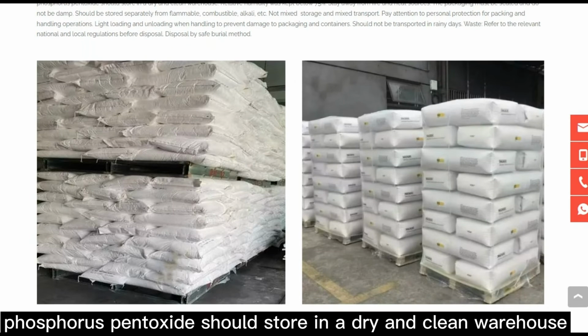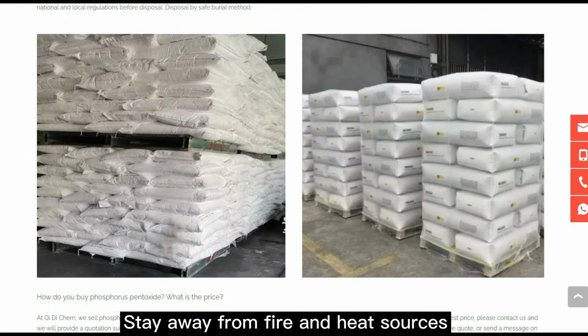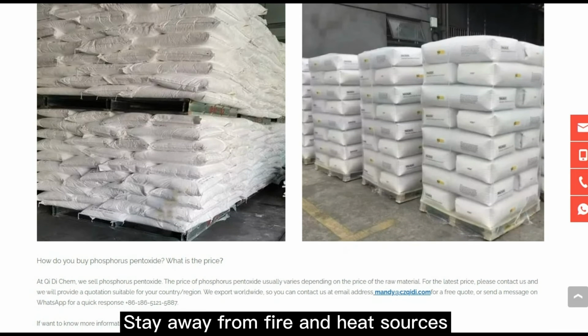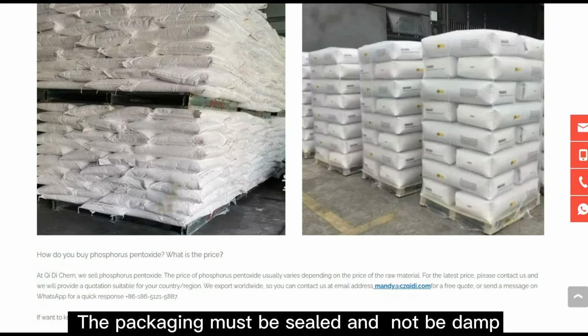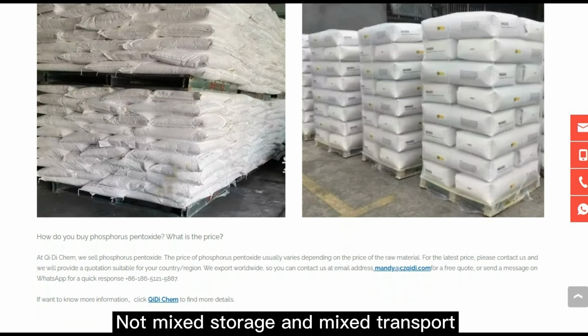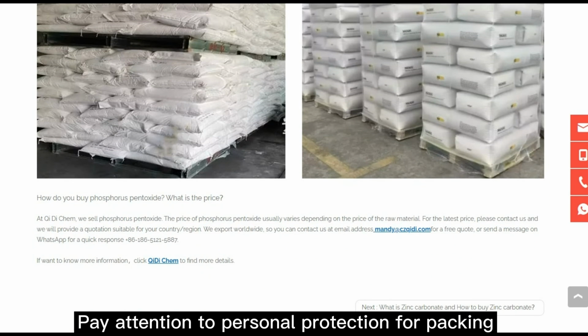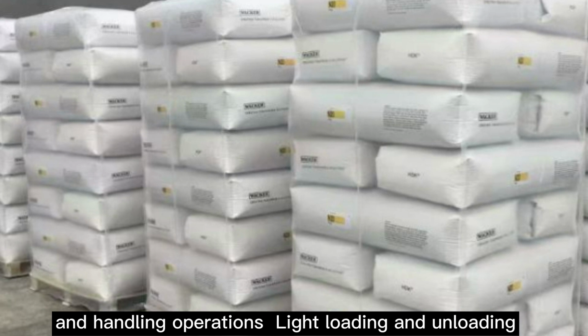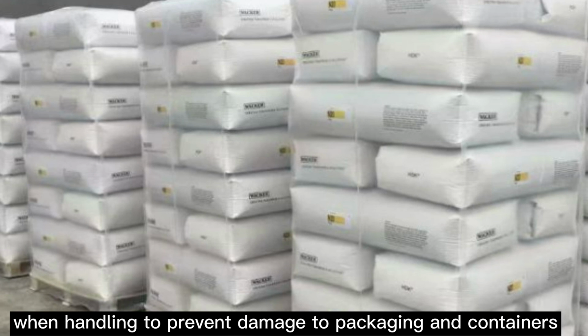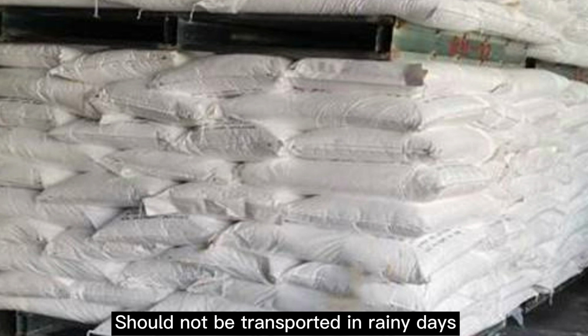Phosphorus pentoxide should be stored in a dry and clean warehouse. Relative humidity should be kept below 75%. Stay away from fire and heat sources. The packaging must be sealed and kept free from damp. It should be stored separately from flammable and combustible materials, alkalis, etc. Do not mix storage and mix transport. Pay attention to personal protection for packing and handling operations. Load and unload lightly when handling to prevent damage to packaging and containers. It should not be transported on rainy days.